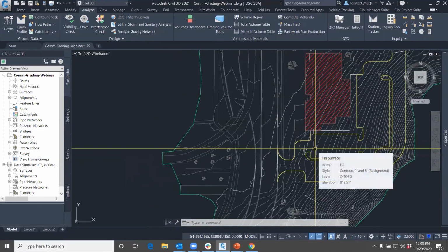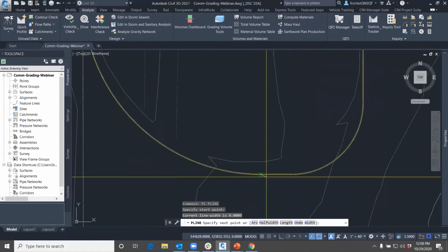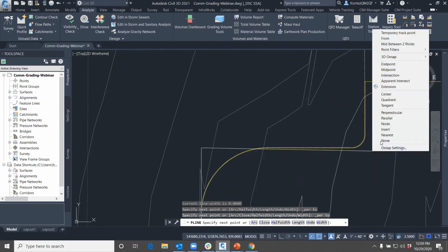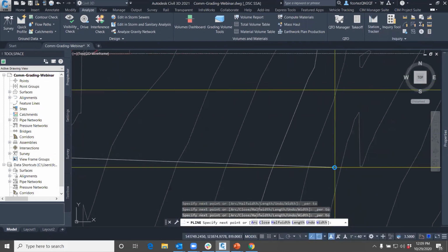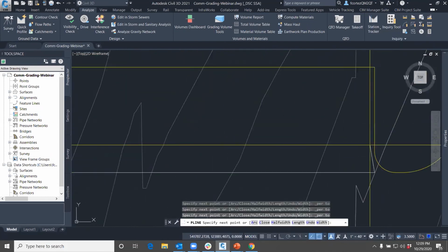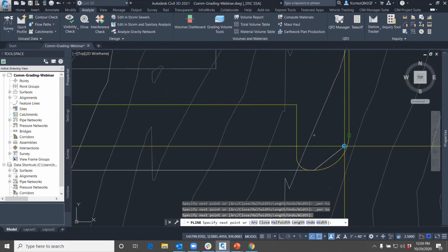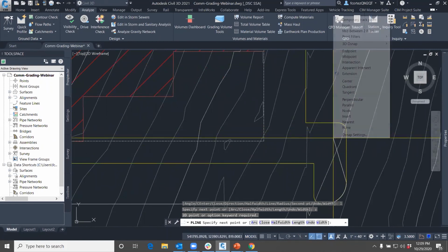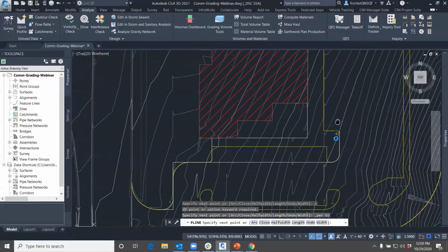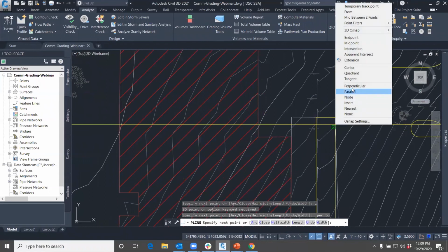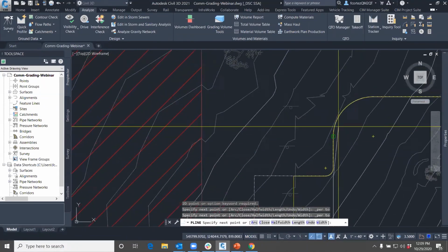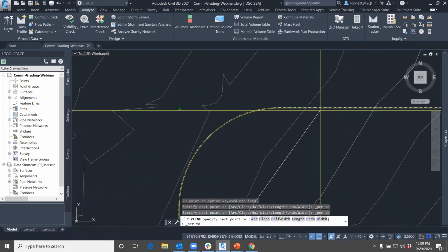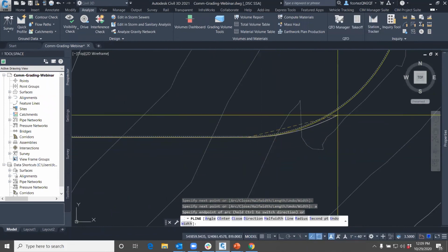So let's go ahead and get started on the initial phase. Let's create a polyline. Start here, and we're just going to go all the way around where we think we're going to want some vertices. And so we could come all the way across here. Usually when we have these long sweeping curves, I will just go along those curves. But typically in construction, a lot of the contractors, because there's a different section for drivable for trucks and drivable for cars, will cut this straight through. So in essence, I'm designing this the way it's probably going to get built. And that could be an advantage for us in the long run.